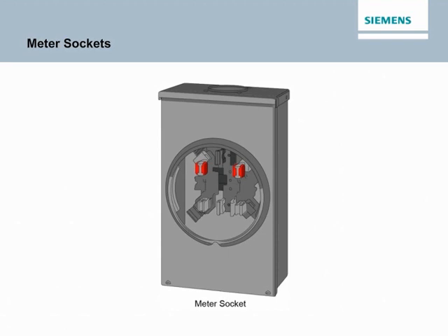Single-position meter sockets are used for single-family homes and in some commercial applications. Multiple-position meter sockets, also called gang sockets, are used in multifamily and other commercial applications requiring 2 to 6 meters. Requirements for meter sockets with maximum voltage ratings of 600 volts or less and continuous current ratings of 320 amps or less per socket are covered by American National Standards Institute Standard C12.7 and UL Standard 414.